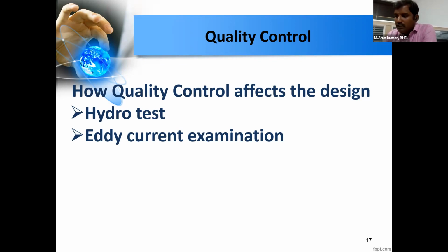So we have heated the water and circulated it for a very long time. Then only we could achieve this plus 63 degrees Celsius minimum metal temperature. And not only that, we have heated the high mass areas to improve this temperature.